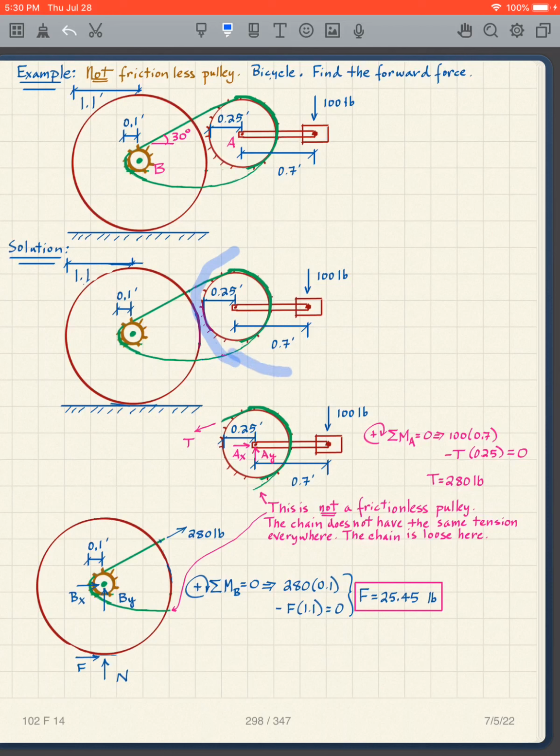And then, I guess the easiest way is I'm going to cut through the axle there. And that frees that up. It's three-dimensional, so it's difficult for me to show, but take a look at your own bicycle, and you'll see that if you cut there, and cut through the axle, you've freed up everything. And so I need to put forces there. Well, I put the tension there, but I made a cut through there, but we've said that there's no tension in there, so I don't put anything.